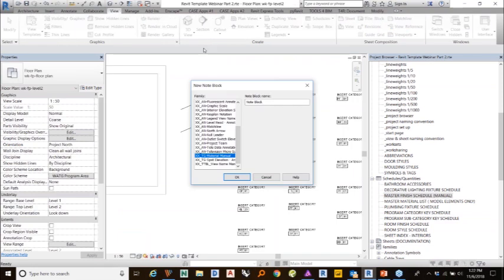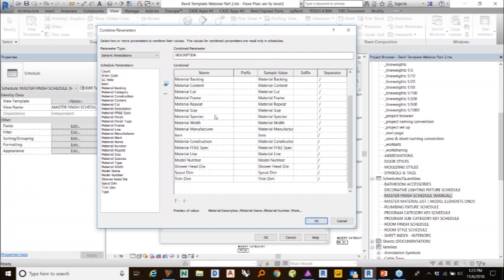I'm not going to get into how I did that. I'm just going to show you the fields. It's pretty simple. I've got a material mark, a material finish type, a GC note, and then my description is a conglomerate of all those parameters that are instance parameters in that tag, separated by this little slash here. So that's all it is, right? But if someone is trying to think about this while working on a project, it's going to take some time, and they're going to have to organize it the right way. Once it's organized, everyone can use this schedule.